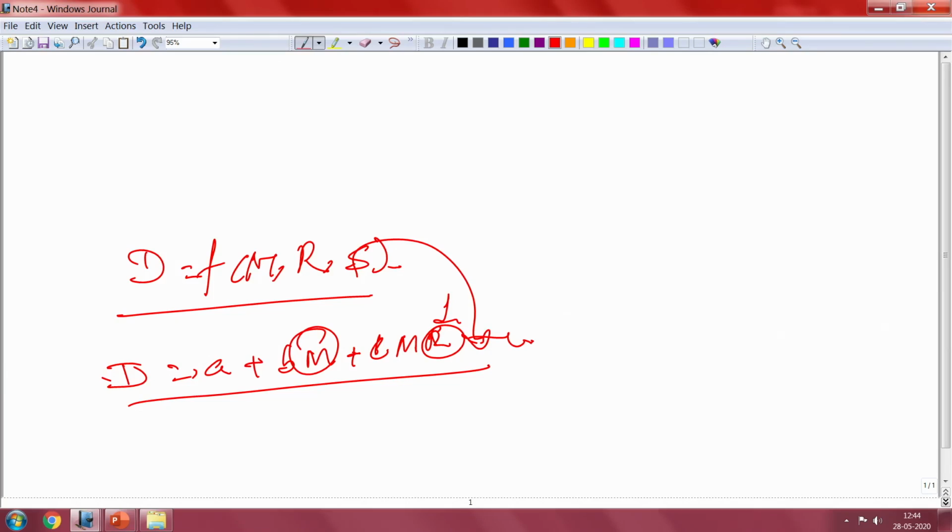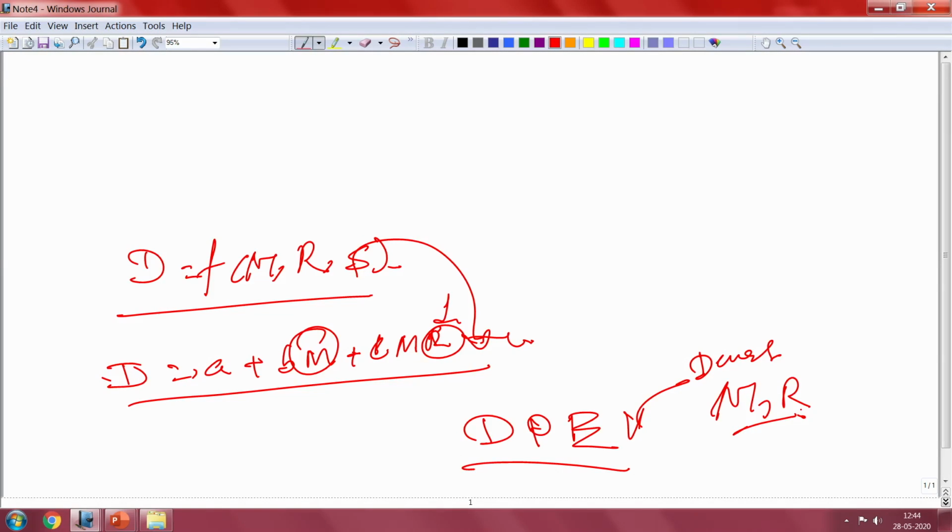That kind of equation will be useful to identify what duration you can expect in the region. Because if you have one record, you will get only one duration estimate. So, if you have a large number of records in the region, you can know how much these durations vary, and what the standard deviation is. This kind of functional form, which is called a duration predictive equation, will be used to estimate the duration you can expect for the given magnitude and distance at a particular location, for the rock site as well as the soil site. So, these are all very important parameters to design.